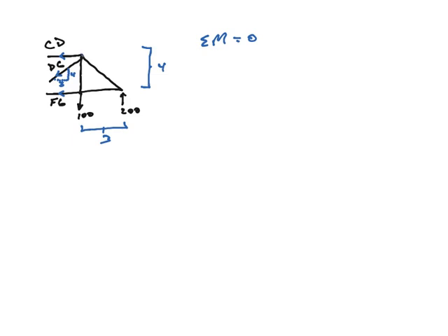Now, we have several different places, here, here, or here. 3 different places we could choose to calculate the moments about. Again, just as is true when we find the reactions, the global equilibrium, you always want to choose that point which gets rid of most of your unknowns. So here, this top point, and I'll do it in red, this red point here has CD and DG on it.